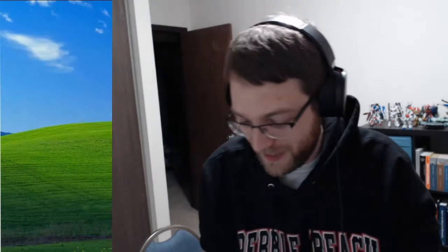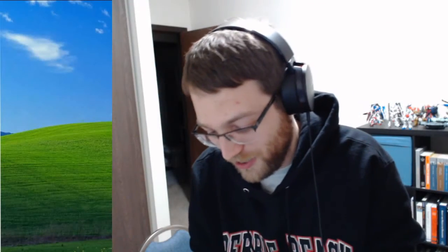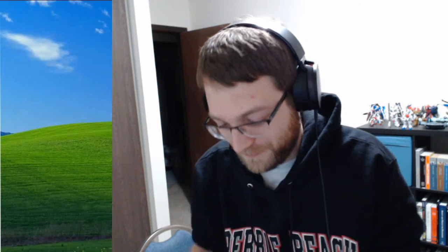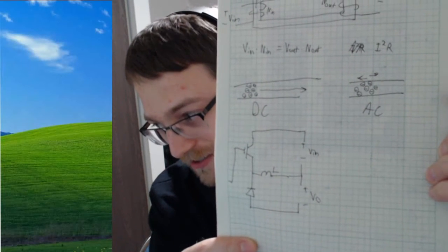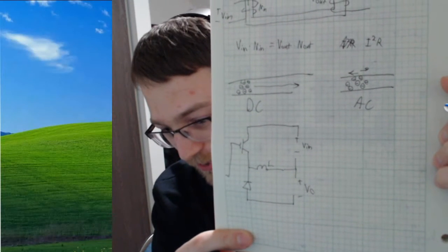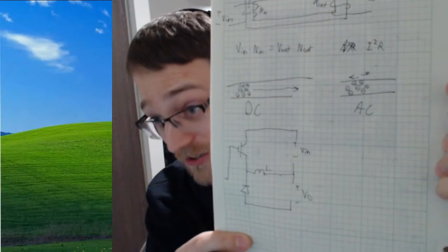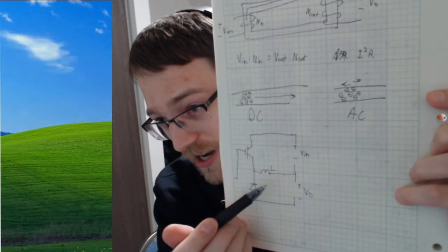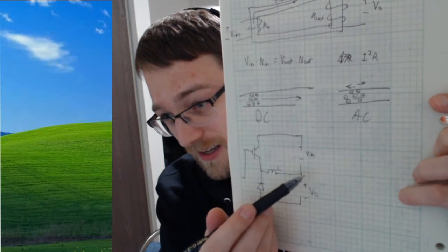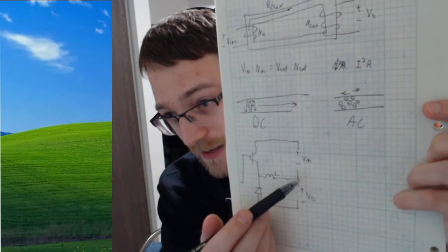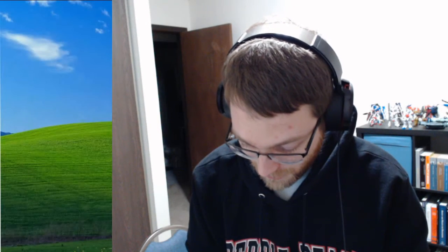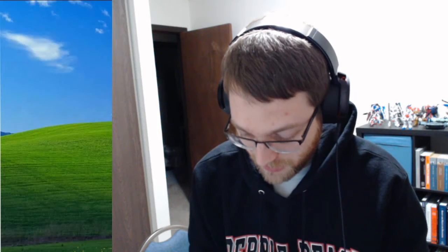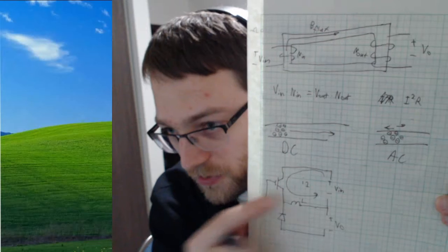There is one configuration I have not yet shown, and it's this one here. What sets the buck converter, the boost converter, and the flyback converter, or as it's otherwise known, the buck-boost converter, apart is what the shared component is that goes to the central leg between the two of them. And the way this one works is when the transistor is on, you have this first current, this I1 here, which flows around through the top.